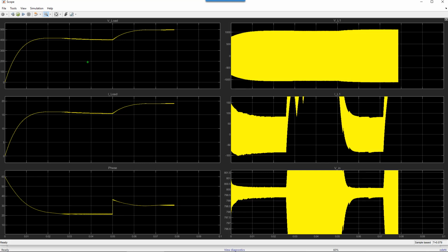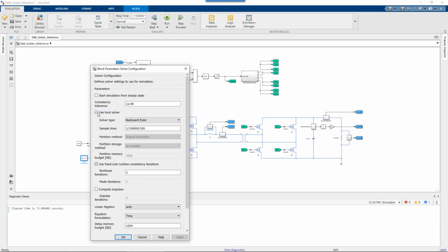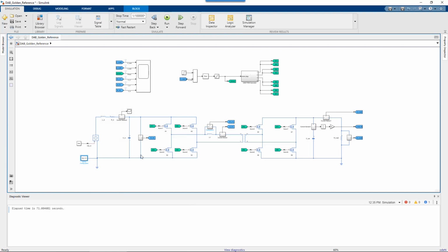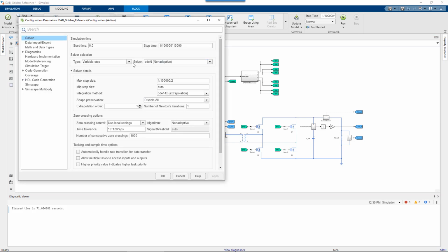The systems should respond in a more continuous, periodic manner, because that's the way they're designed. But this just isn't even useful in this case, so we don't want to use this local solver. At least with that, we'd have to increase the number of steps even more, so it would be even slower. So for this topology, we're actually in general just best using ODE23T.